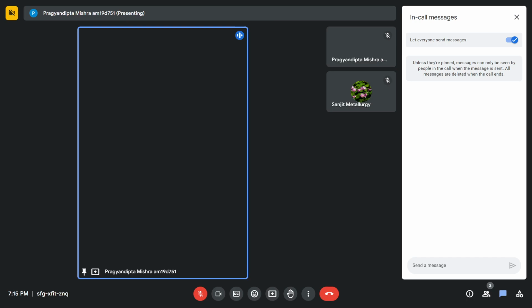I hope this much is clear. Sorry, this is not change in volume. This is change in volume by original volume. So this is your K, and if I say that this is sigma m, I can rewrite this in this fashion, and sigma m will get cancelled. So finally I will have E divided by 3 times (1 minus 2 nu). Yes, so this is the correct relation between bulk modulus and modulus of elasticity, Young's modulus.